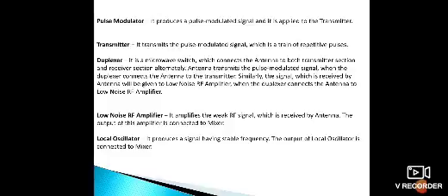Okay, so when the duplexer connects the antenna to the transmitter, similarly the signal which is received by the antenna will be given to the low noise RF amplifier. That means whenever the duplexer connects to the transmitter section, it will work. Whenever signals are received from the antenna and given to the duplexer, it acts as a receiver section only, and the transmitter section will be off. Okay, so that is the work of the duplexer. I have already said in the previous slide what the need of the duplexer is and what its main functions are.